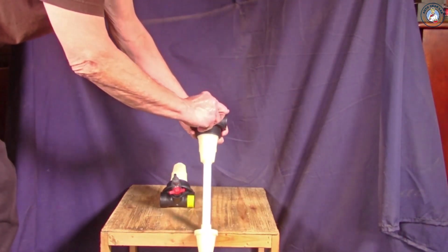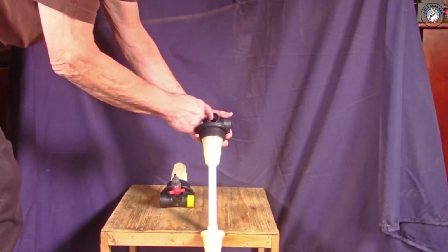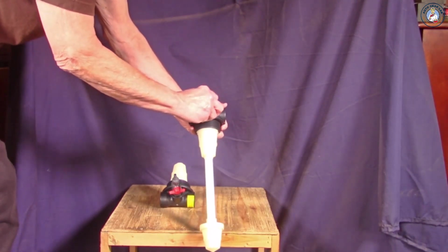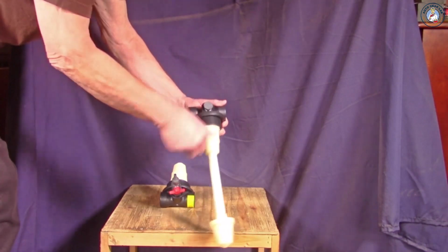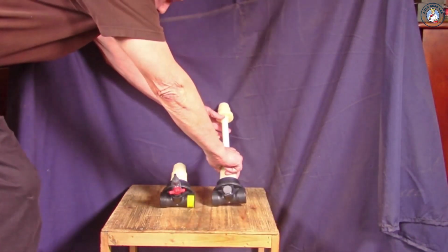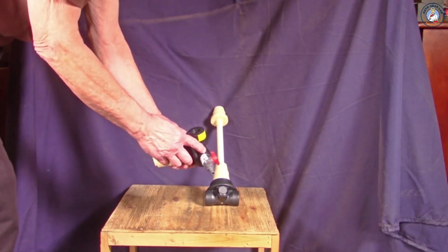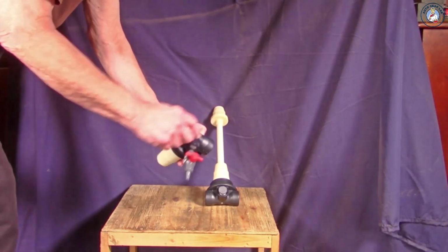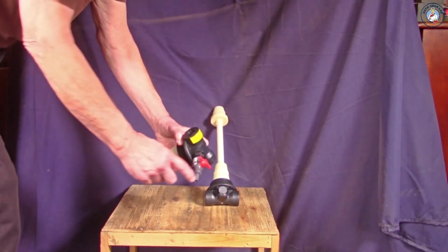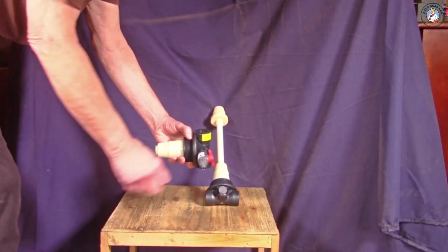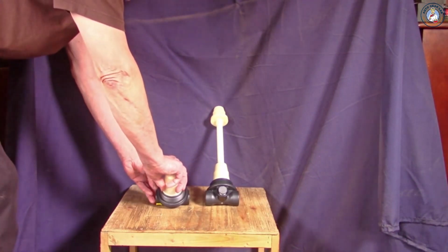The port I mentioned can be used for a second line if you need water for some other purpose, or you can put a sample valve to test your water from time to time to see what the hardness of that water is. You should regenerate your softeners at a maximum of 3 grains. For the carpet business, probably even 1 grain would be good, to keep it really fresh.